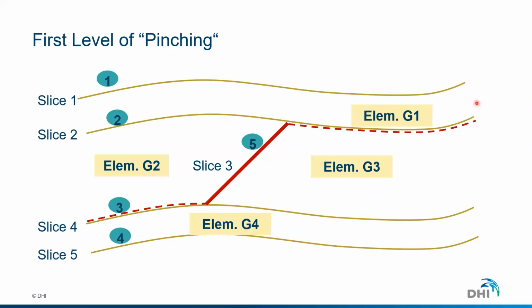A few examples about this. If you would like to put a fault in the middle of your model domain, or a fracture, or any structure, let's generalize this, a surface that is in the middle. That's the way to build a model. You add first the 3 layers, so 4 slices, and then you add the one in red in the middle, and then you interpolate, accommodating to the right slope of the surface. And since you have previously marked slices 1 and 2, 4 and 5 as fixed, FEFLOW knows where to stop, and it will create a zero thickness between the red and the yellow lines.